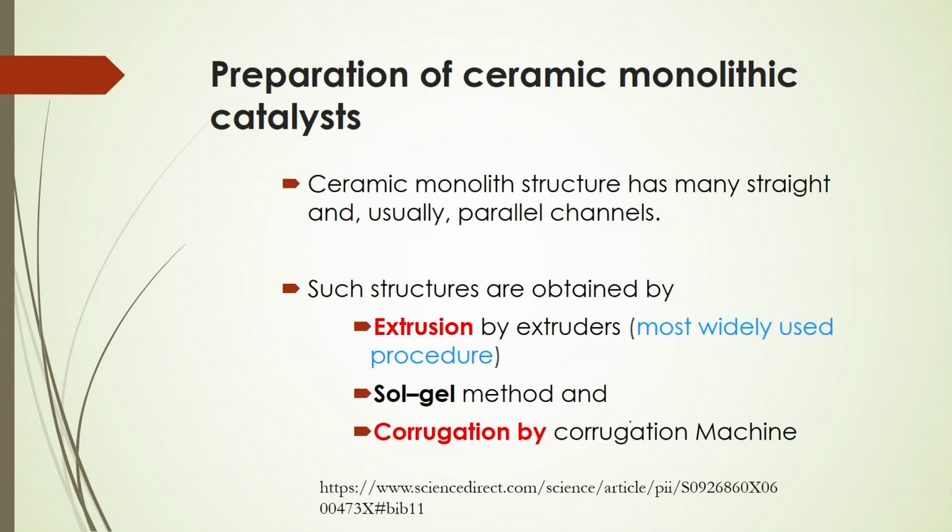Now the question is how to prepare this type of ceramic monolithic catalyst surface. This ceramic monolith structure has many straight and usually parallel channels, developed so that you can expect uniform flow through the channel, slug flow or plug flow type, so that you can get uniform mixing over the solid particles and more efficiency of the reactions.